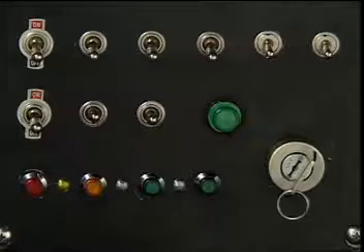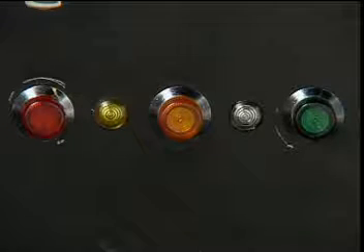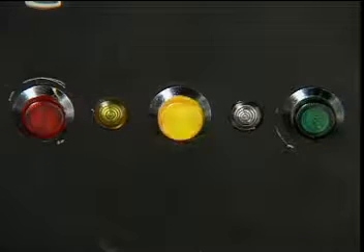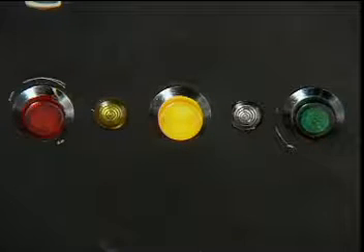The Cummins system has built-in diagnostic capability, which alerts the operator of a system problem while the engine is running by illuminating one of the 3 diagnostic lamps. The yellow warning lamp illuminates to indicate a fault condition that allows the engine to continue to be operated. With this type of fault, the engine can still be operated but may lose some system features, which can result in power loss. This fault should be repaired as soon as it is convenient to do so.